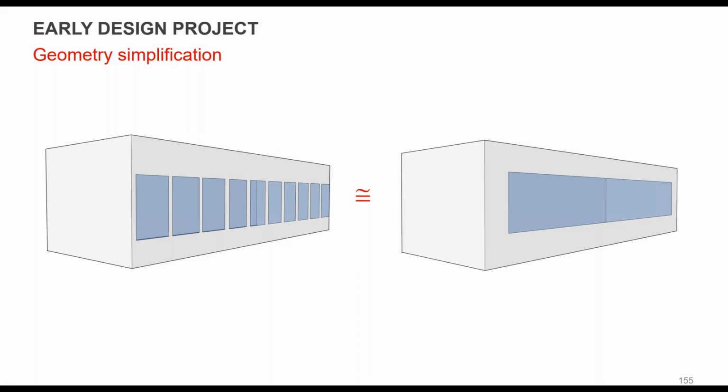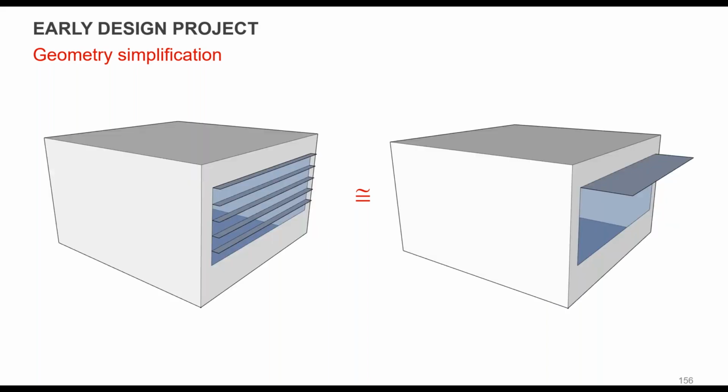One of the critical things is windows are important if they're punch windows like that, if you're trying to look at daylighting penetration, and that's probably not something you're going to be doing a lot of detail on in early design. So the area of windows can be just represented as a single window, or instead of individual shades, you could create a single shade that's more effective. This makes it easier to create your input, and also will help you meet the goals there.